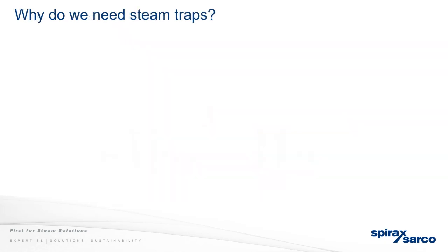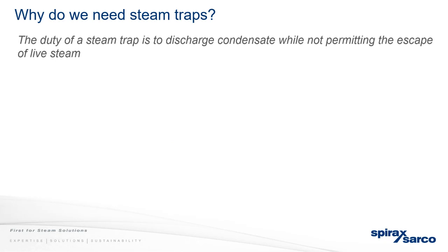So why do we need them? As I just touched upon, the duty of a steam trap is to clear the condensate. It connects to the steam system so it doesn't allow any steam to escape and ensures that they stay separate.